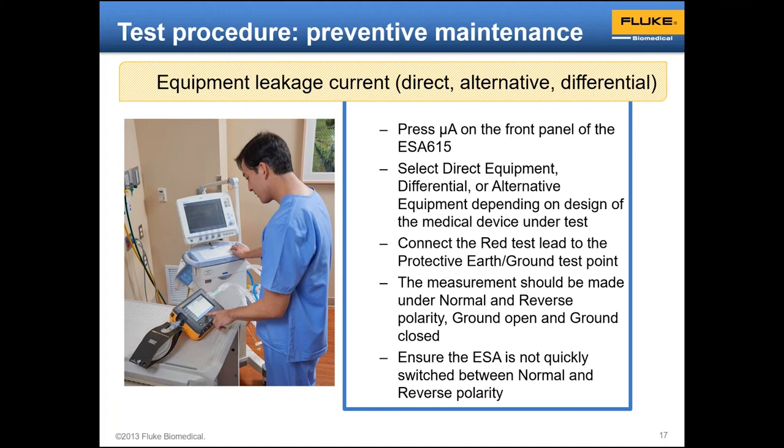Now be careful switching between normal and reverse polarities. There's actually a delay built in, and you go through an off position on the electrical safety analyzer to prevent sharp current impulses from damaging either the medical device or our safety analyzer. All right, so we've measured leakage to ground.